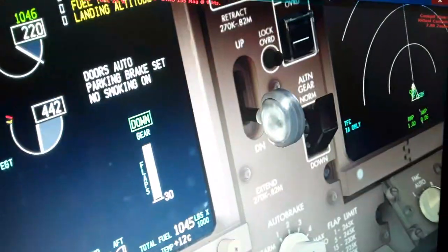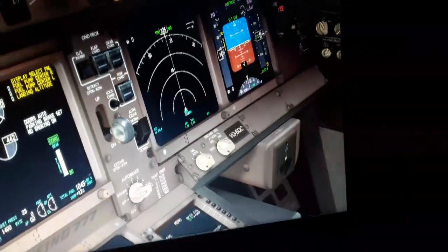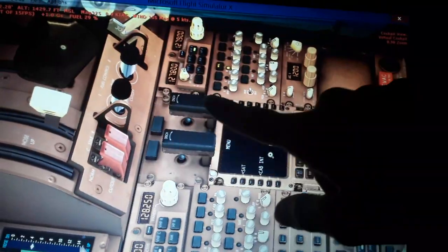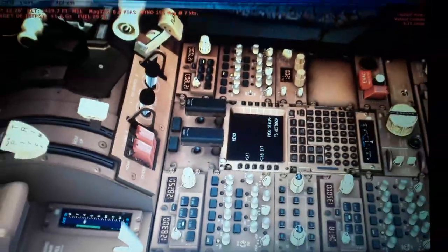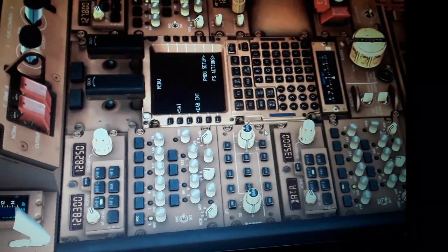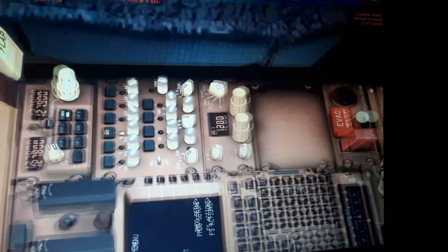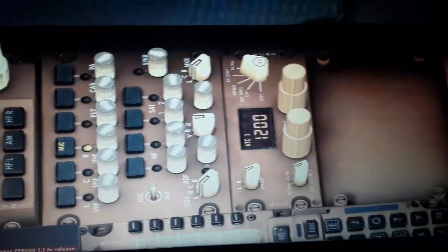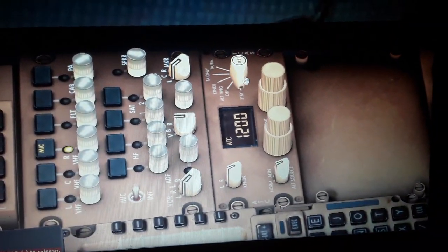I will tell you about the rest of the stuff now around the cockpit. You can see we have the fuel control for the engine, the left and right engine cut-out switch, the fire extinguishers for the left and right engine. We have the parking brakes turned down like this. We have the weather and terrain reflections, the radar of the aircraft. We have also the TCAS system, the traffic collision alert, that receives and transmits our position and receives from other aircraft or the traffic control.